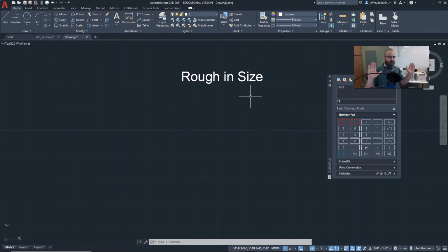They don't want it to just barely fit, because then what happens when the wood swells in the summertime, when there's a lot of heat and humidity? Then it's going to be hard to open and close your doors. If you've ever been to a house like that, it's probably because something related to that wasn't constructed properly. So we need to leave that space for swelling, and we also need to make sure it's straight, so we need some wiggle room.